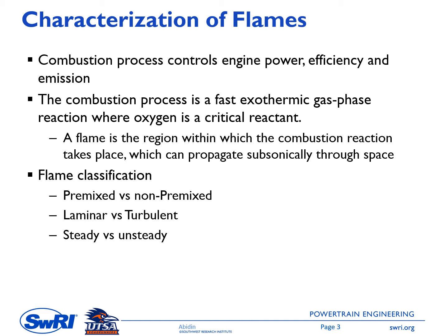Flame classification can be based on the condition of the mixture. So we might have a premixed flame. This is the case for the spark ignition combustion process. When the spark is ignited, around the spark plug gap is a premixed mixture of the fuel, air, and maybe EGR.